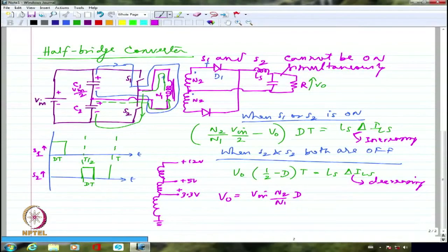This side is power ground, whereas this side is going to be electronics ground, which is low voltage and low current compared to what I will have on this side. This will be high voltage. Right? And if I want negative voltage, then I might have to just make it the opposite way. I will ground the positive terminal and the negative side will actually be available as the negative voltage. That's it.